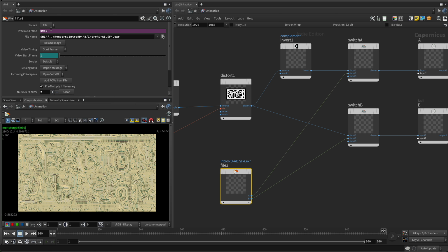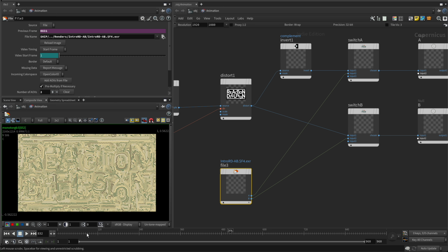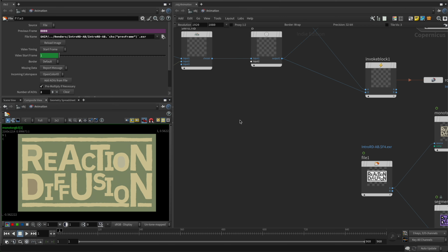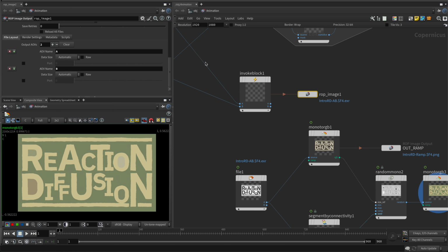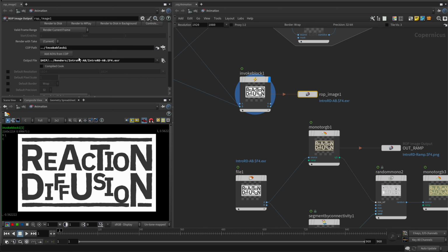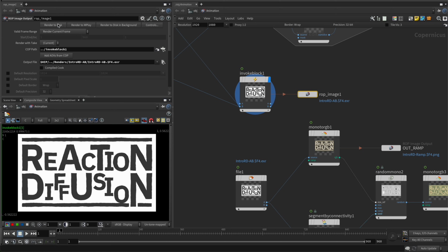Now we've got 1 frame less than whatever's set in our timeline. And the last thing we need to do is to plug that value into our file name expression by replacing our $F4 with backticks containing a channel string for the previous frame parameter. And there's one last detail to take care of back on our ROP image output where we're writing out our A and B values. We need to go to render settings and turn off save in background. And this makes sure that when we're rendering the whole frame range that each frame writes out completely to disk before the next frame tries to read it in. And with that, we're ready to kick off the full frame range with a constant cook time per frame. And once that completes, we can kick off the renders for our final looks.